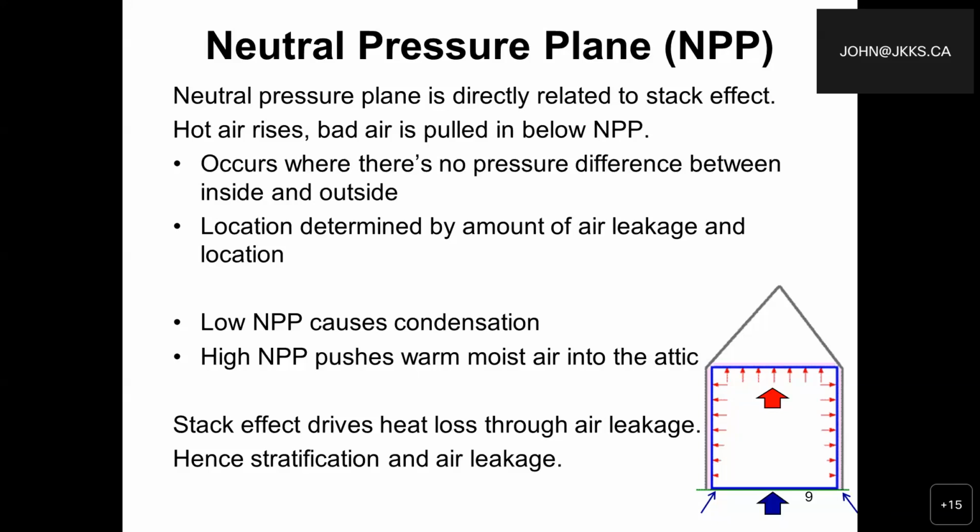So again, as this air is trying to be pushed out through different cracks and crevices, even within the ceiling, or, as I mentioned, through air leakage points. By the way, those air leakage points could even be the electrical outlets on the outside wall, along the baseboard, at the floor. So those are all potential air leakage spots. So again, this is what stack effect is all about.